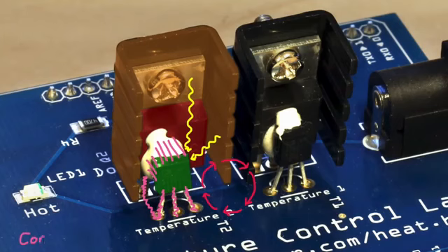We shouldn't need to worry too much about the impact of convection because the conductive path through the epoxy should dominate. When you're running a test, you should take note of how that test differs from the real operating environment. It would be a shame to design a control system that could perfectly control your test bed, only to find out later that the real hardware in the real operating environment doesn't behave the same way.